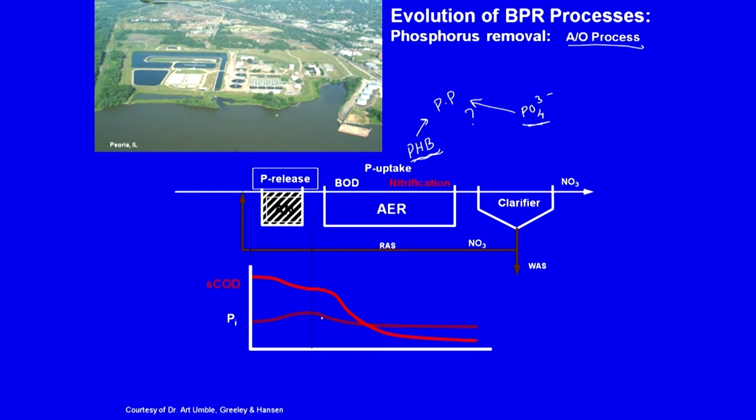Again, phosphorus will be taken up, that is why it is decreasing, but as you see, the net removal is not great. Why is the net removal of phosphorus not very good? Well, because when you are recycling it here, there will be some oxygen here and also nitrate certainly, right, and that nitrate is coming into the picture here. And as we looked at the thermodynamics, if you have nitrate or the relevant electron acceptor, like some oxygen or at least nitrate, they do not let your phosphorus accumulating organisms thrive.